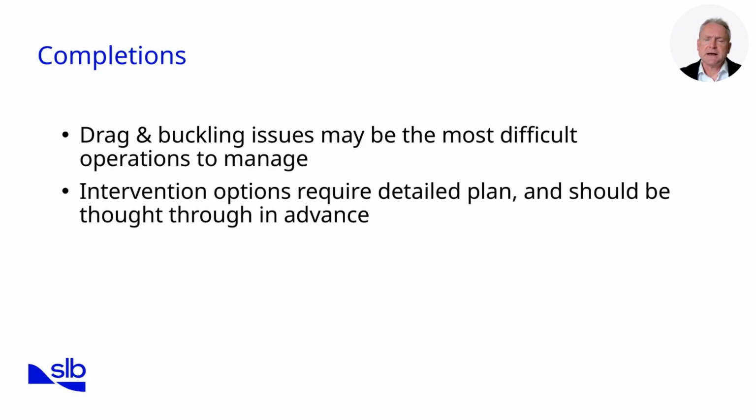This means thinking ahead about wireline, coiled tubing, or tractor conveyance options in case tools cannot reach bottom under their own weight. Intervention in extended reach wells is always more complex, more time-consuming, and more expensive, so planning every scenario is essential. Overall, completions in ERD wells require not only engineering analysis, but also operational creativity, balancing mechanical limits with the need to achieve reliable zonal isolation and well productivity. With completions covered, we now need to step back and look at the bigger picture, the project and operational challenges that frame all ERD activity.